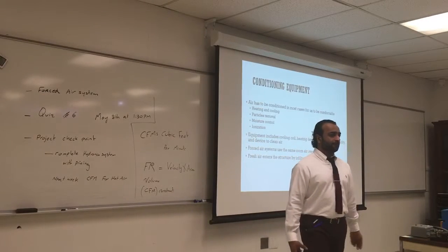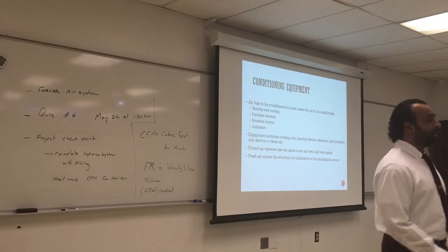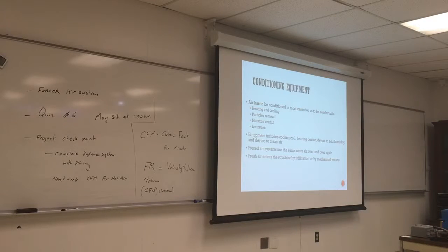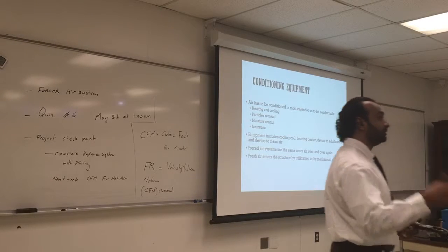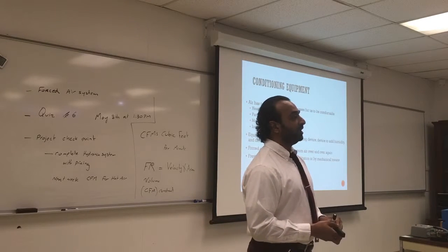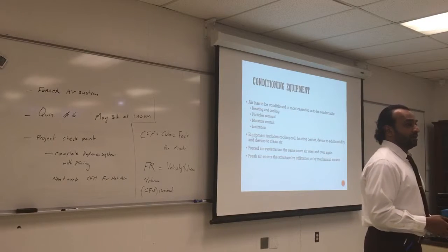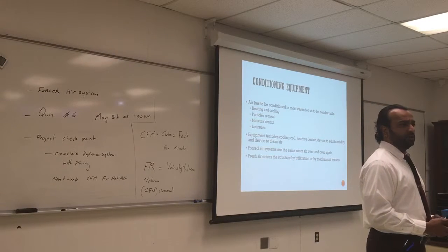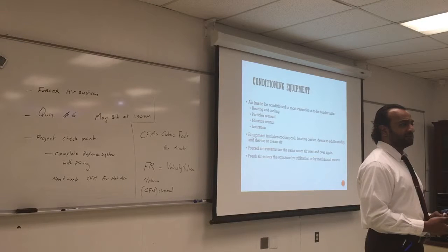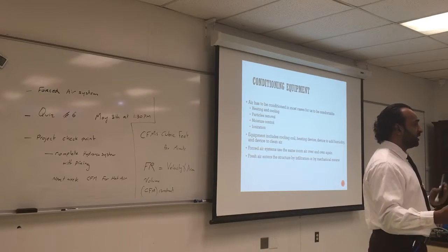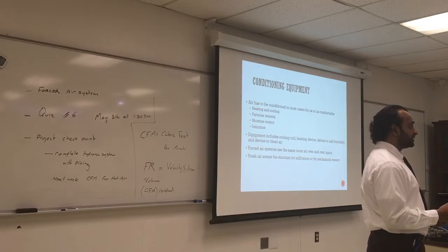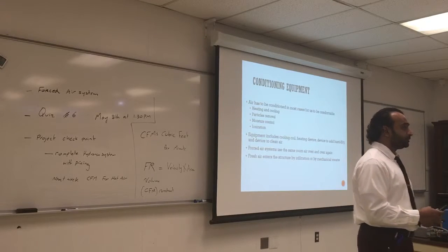Why? It's better to have controlled air coming into your house, especially this season now. We have pollens all over the place, allergies. You want to introduce air that is free of pollen. You need some kind of filters. HEPA filters came, I think, in the early 2000s. How do filters work? You basically have different pressure from one side to another, and you have small openings, a small porous material that will capture all the particles.